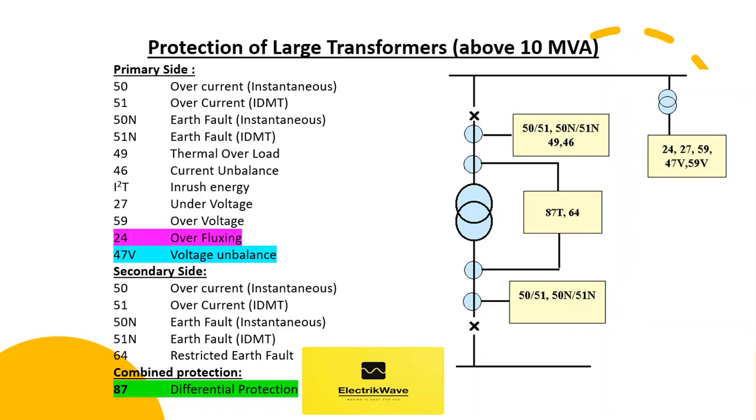It may so happen that a differential relay can trip whenever the transformer is switched on. This is due to the magnetizing inrush current flowing only in the primary side of the transformer. To avoid this, the relay should have a second harmonic restraint facility. Similarly, a fifth harmonic restraint facility in the relay will help avoid a differential trip during temporary overfluxing conditions.